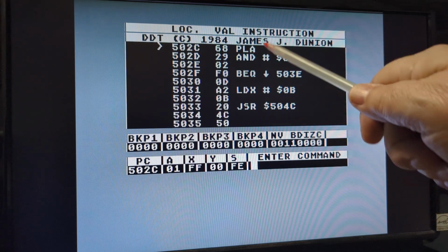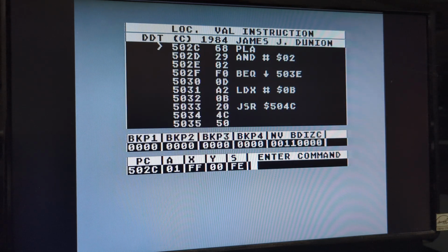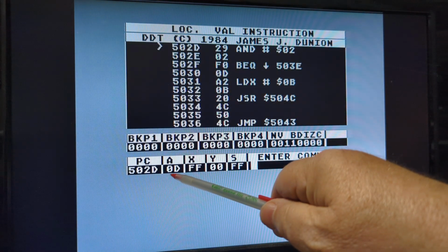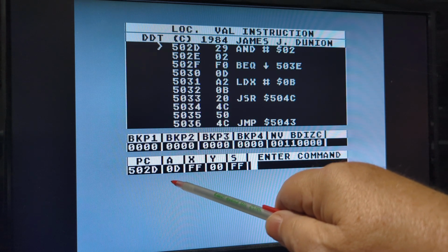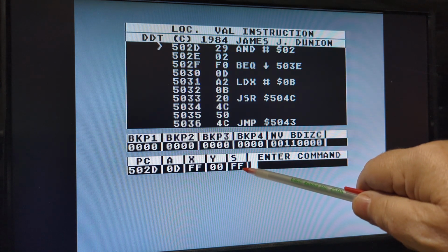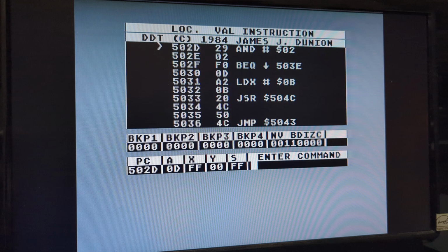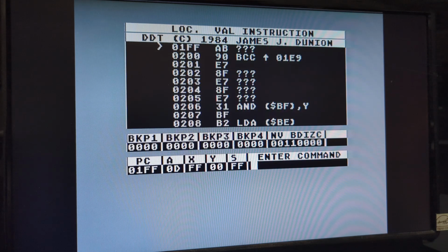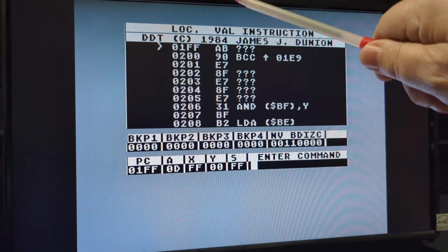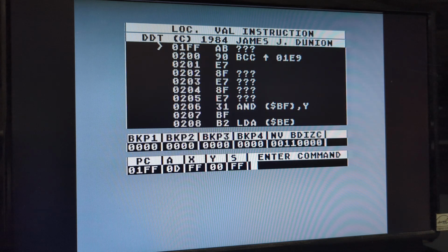It's going to pull the value off of the accumulator. So this goes to 13, back to 13. The stack pointer goes from FE to FF. And if I go look at 1FF, you remember the AB that got pushed to FE is now back in FF.